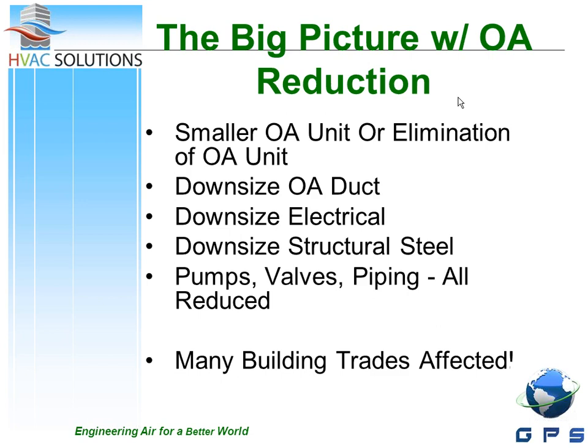Not only are you downsizing the amount of outside air you have to bring in, that could mean less ductwork, less electrical, less steel. You're affecting a lot of other things that we don't always look at.